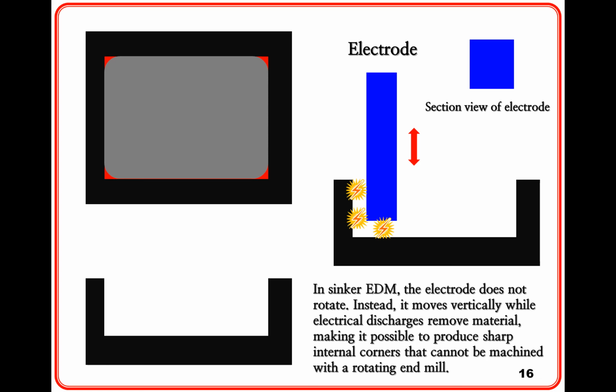Electrical discharge machining requires an electrode. Generally, when the workpiece and the electrode are connected to the positive and negative poles, electrons are emitted from the negative electrode and move toward the positive electrode. As the electrons travel through the gap, they collide with other particles and cause ionization.